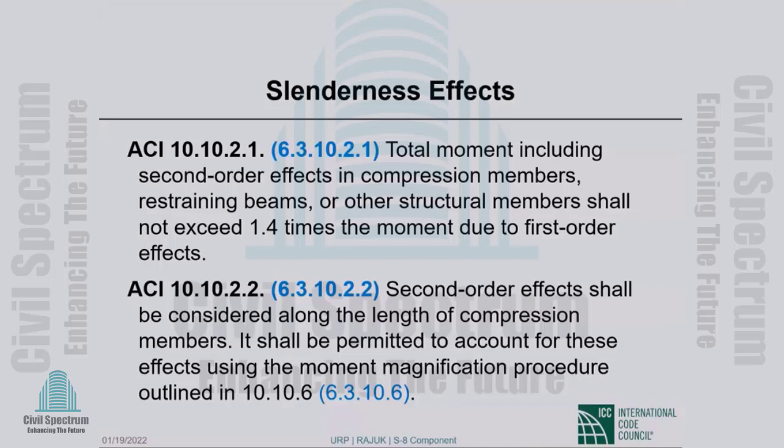The concern is beyond that. If the moment, including slenderness effects, is more than 140% of the first order moment, there is potential instability, and we do not go there.